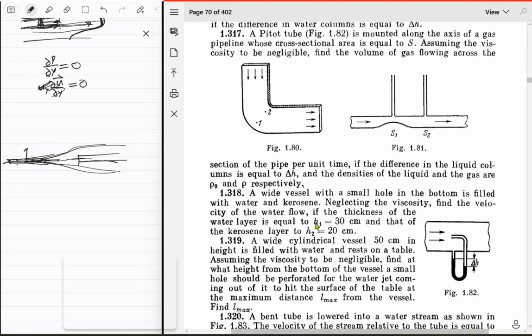We don't even need to show that the vorticity is not zero everywhere. It might not be, who knows. Already you have viscosity, which means you can't apply Bernoulli's. So the way it's usually done is just wrong, in fact. Unless this actually doesn't interact with the tube at all, in which case it would be correct. But that doesn't look likely.